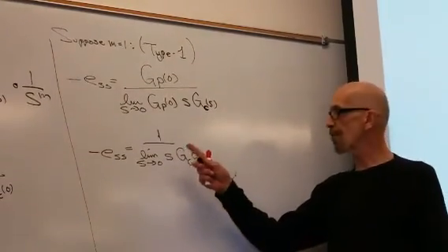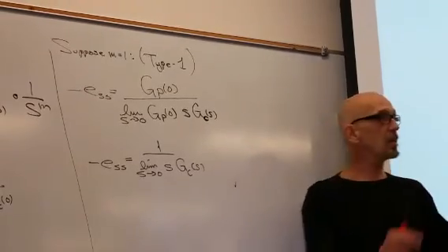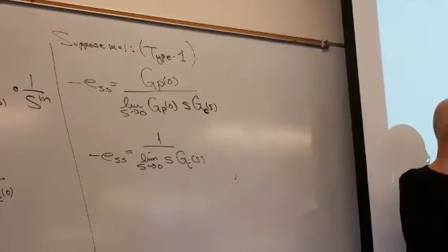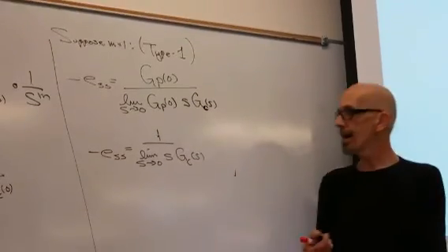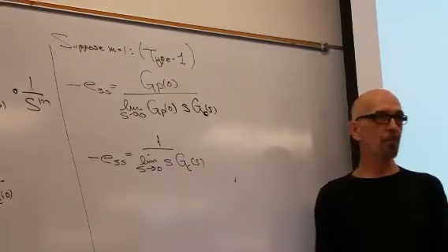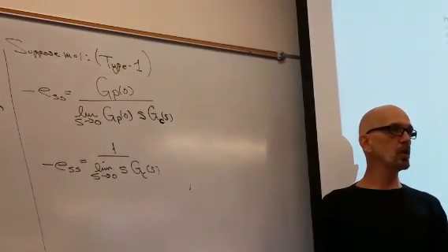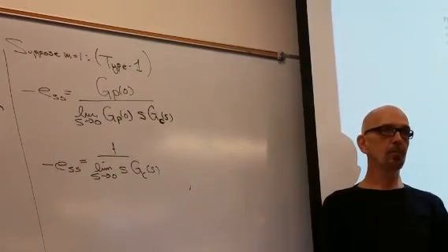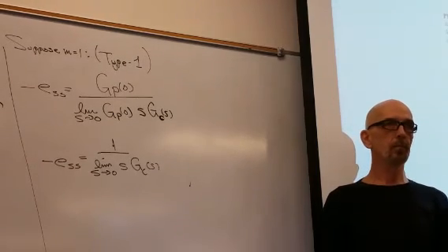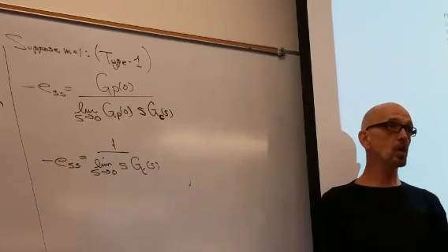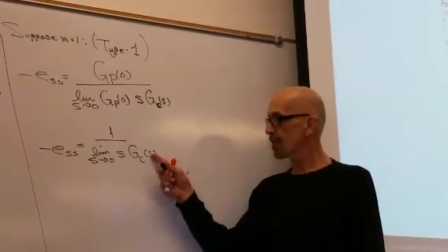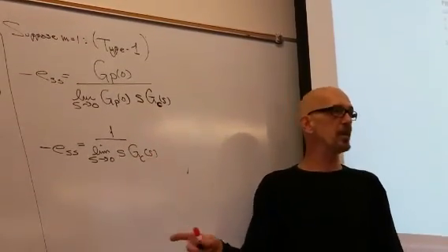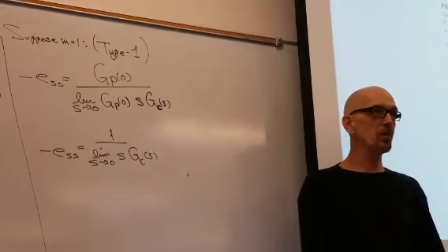So if this thing is going to be finite, because remember, we said the closed loop is type 1, that means the error is finite, non-zero. How is the only way that this thing can be finite? What do you know about the structure of GC of s? It has to have a pole at the origin. Because if it doesn't, this thing goes to 0. You have GC of 0 times 0. 1 over 0 is infinite, and you don't have a type 1 system.